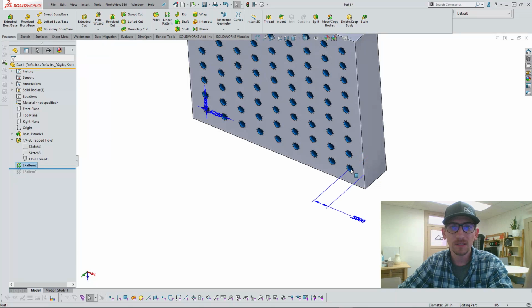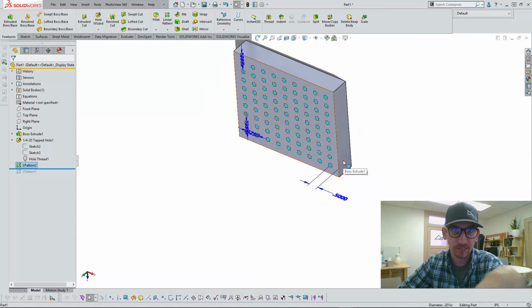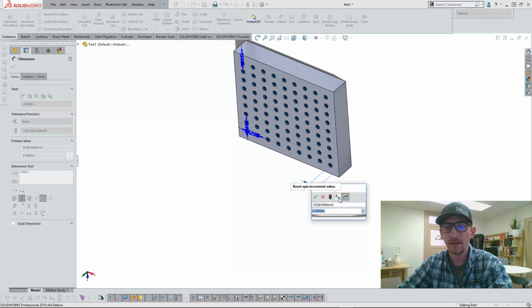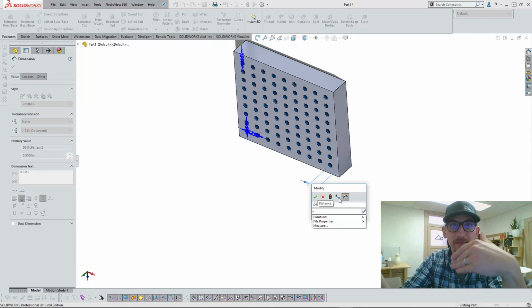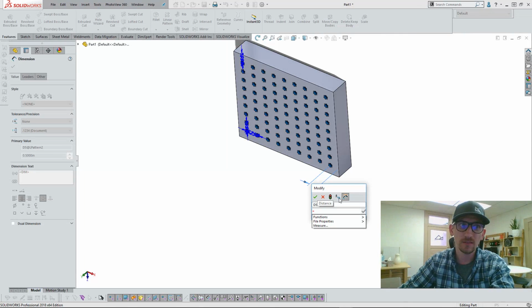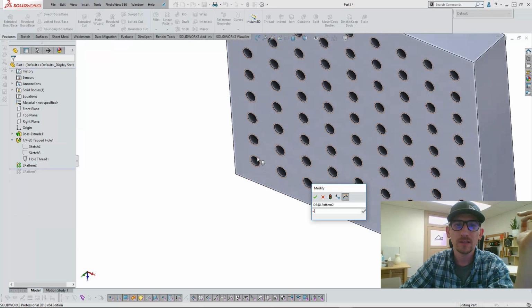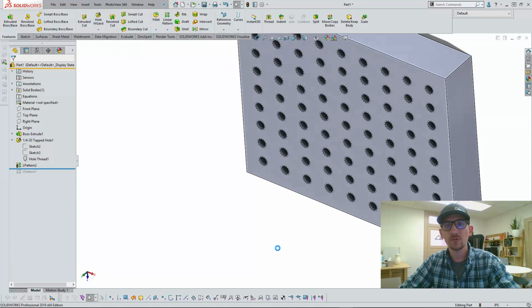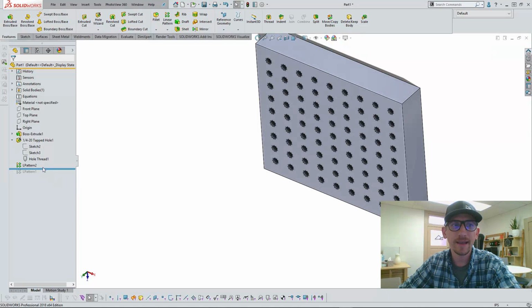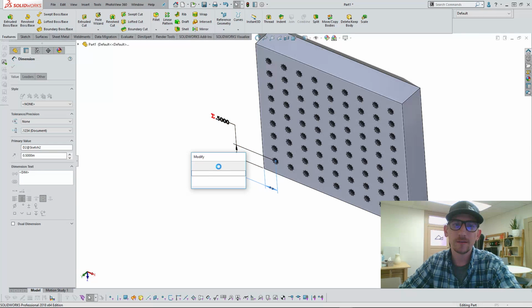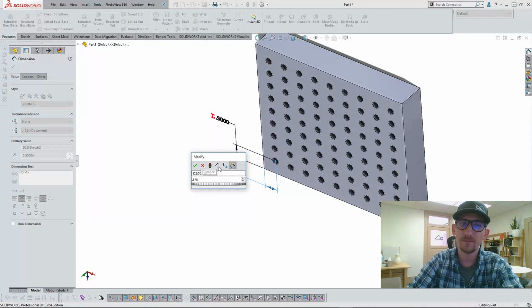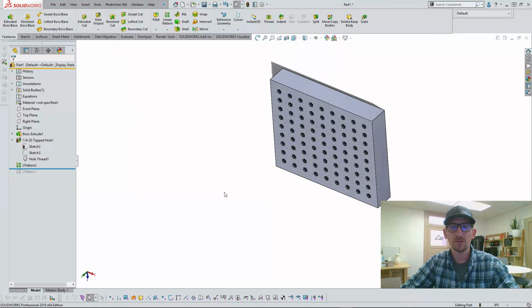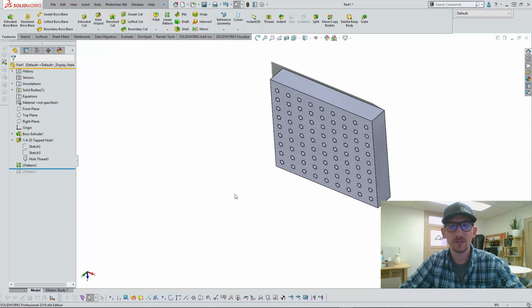Same application. Simply double click on the hole of your linear pattern, double click on that 0.5, push the equal sign to activate the equation function within SOLIDWORKS. Come back over here, double click on your seed hole, see your 1/2 inch there, say I want to make it equal to that, do a Control Q. All right, so now with that, if I came into my first sketch, Sketch 2, and said, hey, I don't want that to be 1/2 inch, instead I want to make that 0.375, so 3/8 of an inch, push Control Q. Oh, Control Q. There we go.